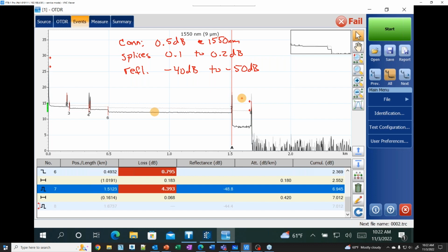It's important to know that there are these values, right? So knowing the limits is incredibly important. For span information, you can get it from the OTDR, but it's better to get it from a continuous wave source. But for span, a lot of folks go with 0.25 dB per kilometer at 1550. And so this is the 0.2 for the fiber. And then if you move it up to 0.25, you have some margin to account for splices and connectors. Be careful with this value on short links.